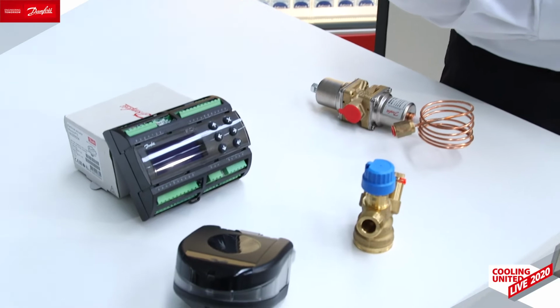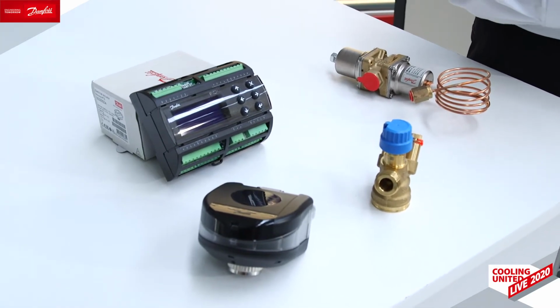One of the biggest challenges that we've actually seen in these types of systems is that we have unbalanced systems. And what we mean there is that the flow that's provided by the pump station will always take the path of least resistance. And to manage the flow, it's important to have pressure-independent balancing valves in the system. If the flow is all going through the nearest case in the store, then you won't get enough flow to the cases at the front of the store, and you will not be able to manage temperature in those cases, so leading to food loss.